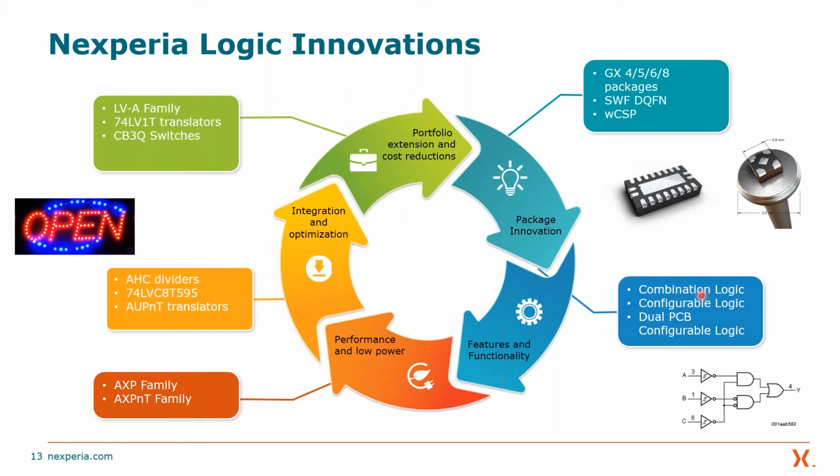Other things are like configurable logic devices, a device which can take on the properties of a different logic function depending on how you wire it. You don't program it, but if you hook the pins up one way on it, it acts like an OR gate. You hook up other pins on it or ground certain pins, and it acts like an AND gate or an exclusive OR or a buffer. So you can buy one device, use it on multiple places on your board, and each place on the board, it has a different personality. That's the way that you innovate logic, by continuing to change its functionality.